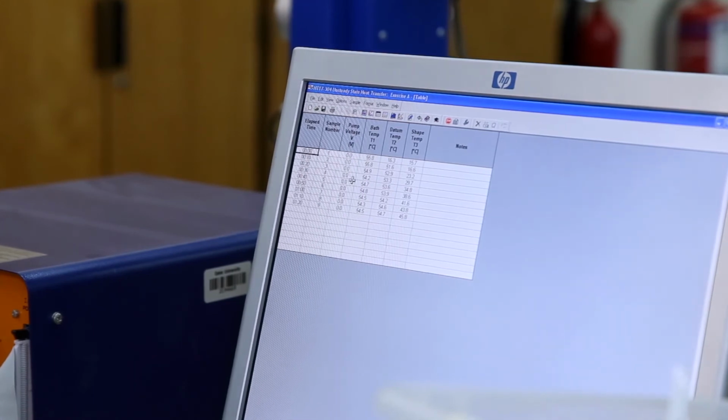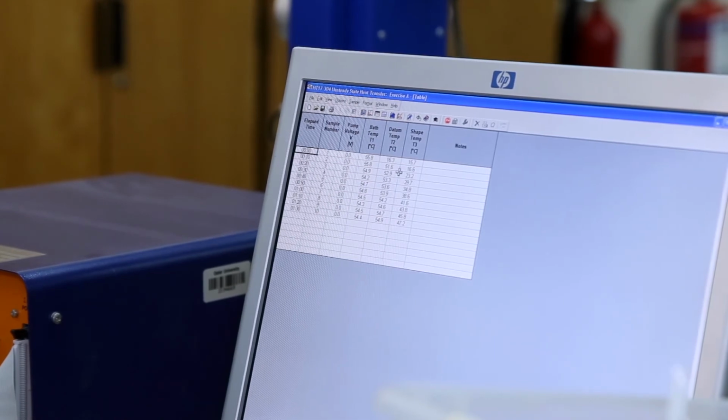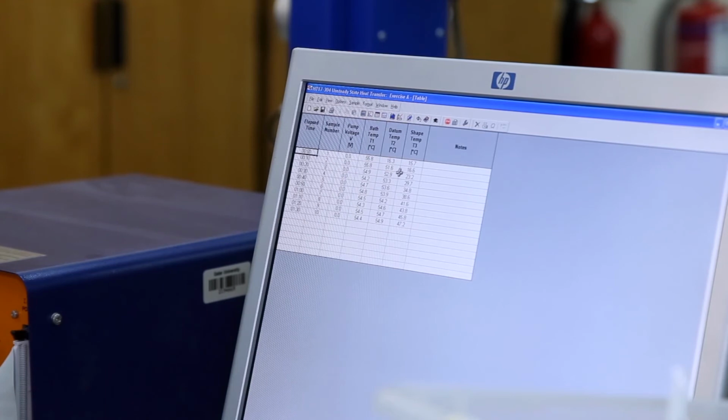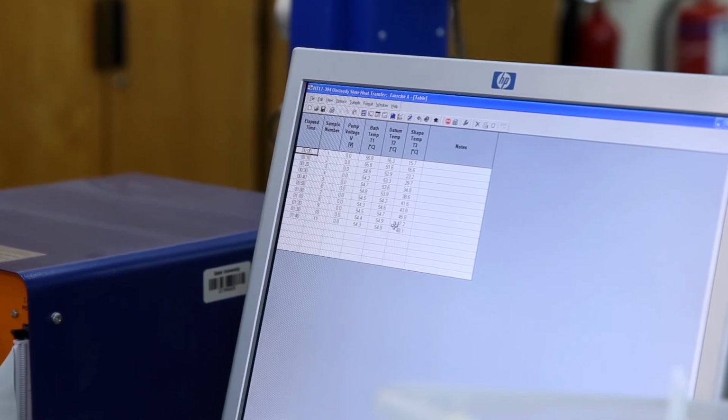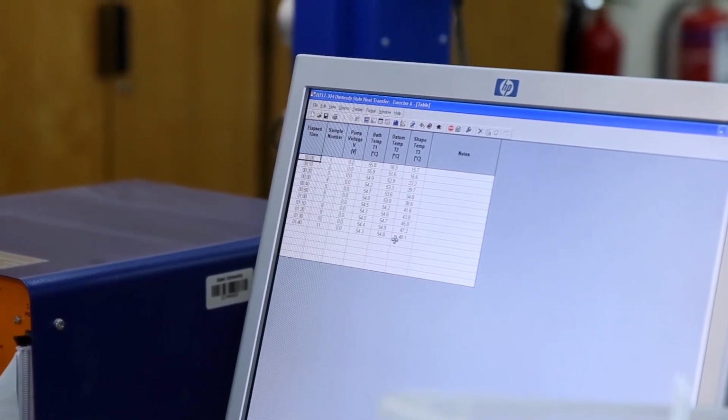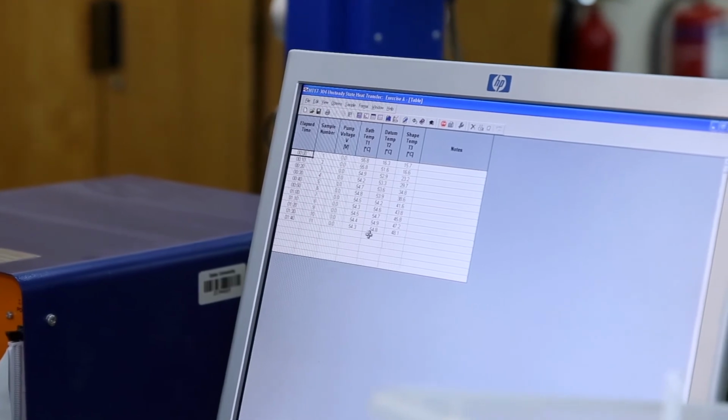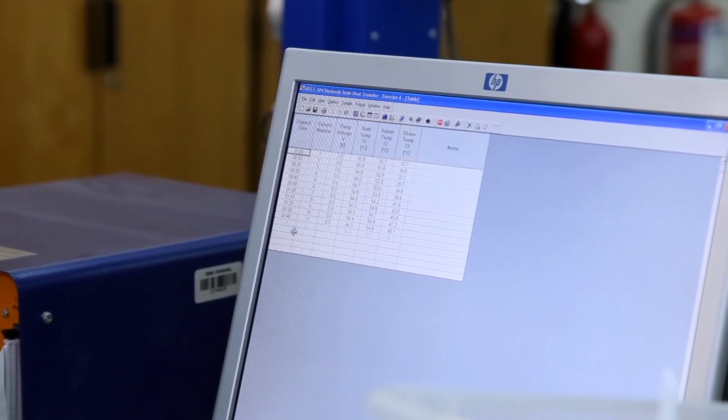Now, as you can see, the driving force becomes less. If you take, for example, the difference from 16 to 23, it was huge. Then here the difference becomes less because the driving force becomes less as we almost reach the bath temperature.